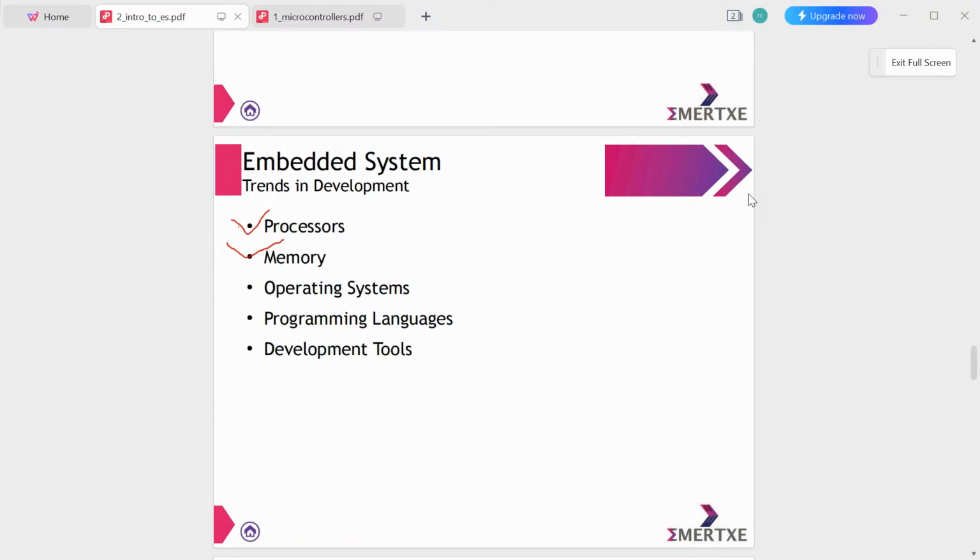Now let's say, people, my data is going to be consistent and just a few bytes of data I want to keep rewriting. Then which memory is the best suitable for me? Don't you think in this case my choice will be the EEPROM? Few bytes, small amount of data. If you keep rewriting it, then the best solution will be the EEPROM.